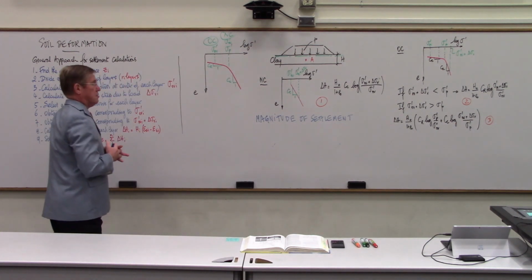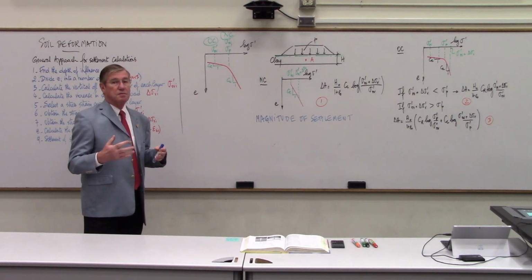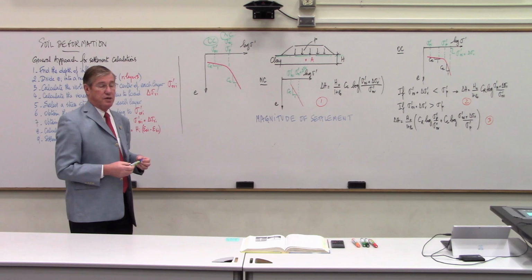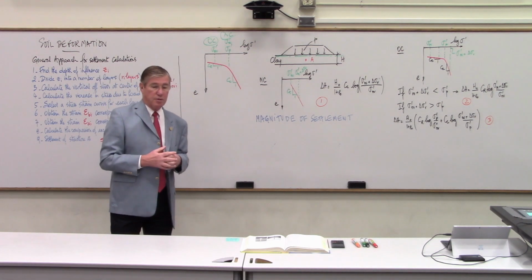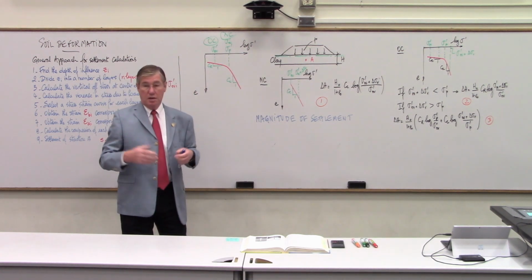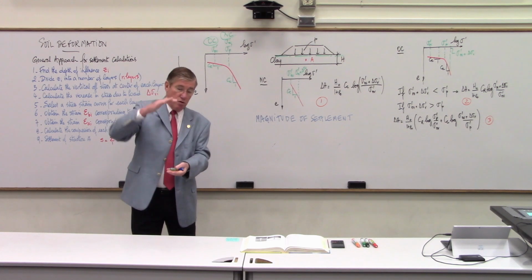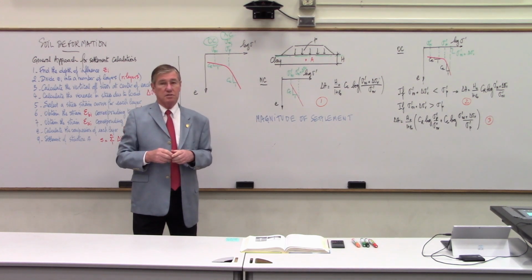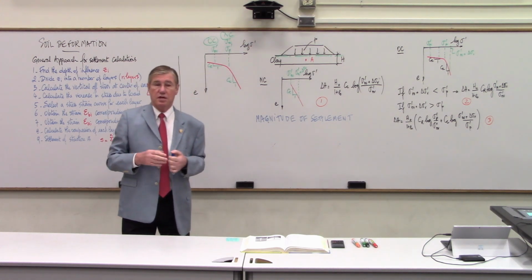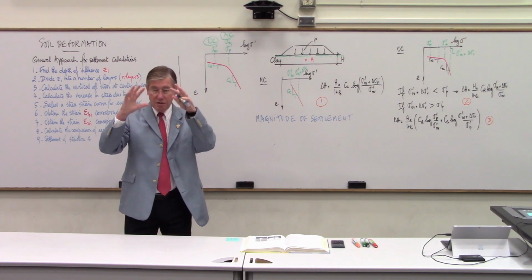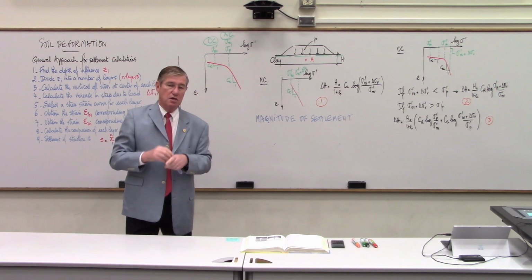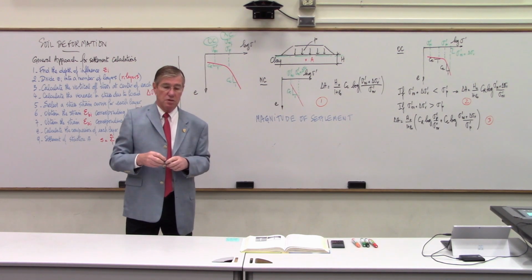The other part of the consolidation theory is to estimate the amount of time that it takes for the settlement to take place. Because as I explained in a previous lecture, when you load these materials such as clay that are full of water, saturated, the water has a hard time getting out immediately out of the pores, and so it takes time for that water to get out, and as the water gets out of the pores, the settlement takes place. So the settlement is directly tied to the drainage of the water from out of the pores between the particles.